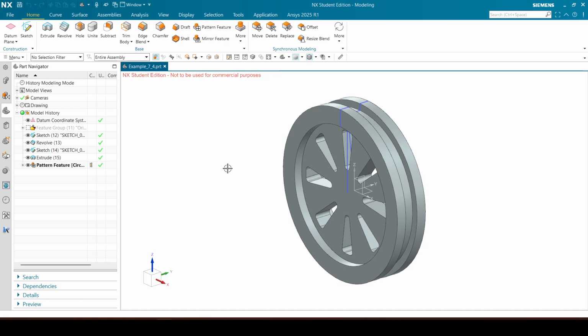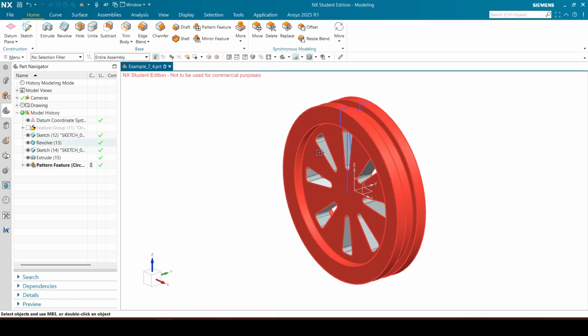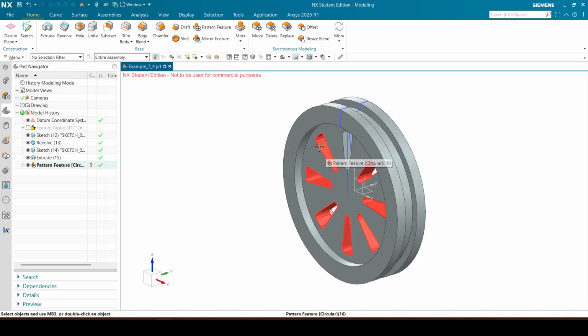And just quickly also check here. Yes, so let me just quickly check there. Oh, I see I misspoke earlier with that 5 radius at the top. Over here I called it a chamfer. It was not a chamfer, it's an edge blend, because I got confused when I didn't see a dimension for the edge blends over here. So it's all 5 radius edge blend, not a chamfer. So apologize for that.